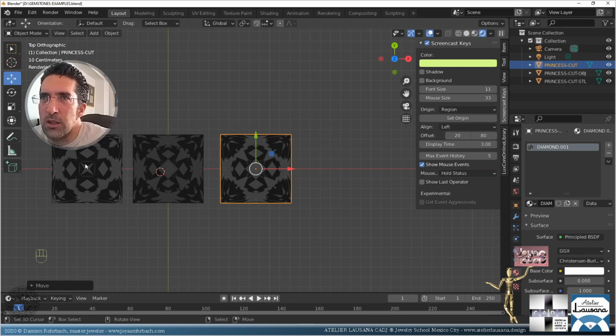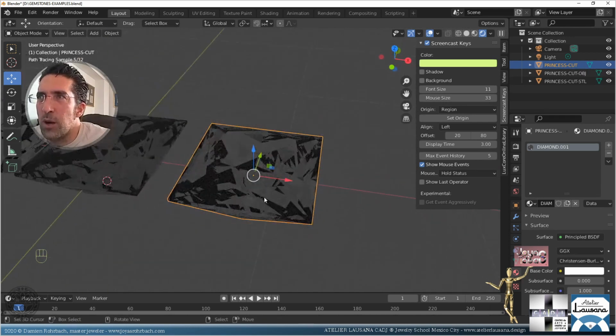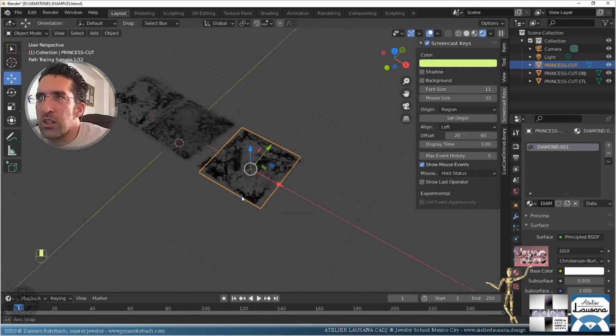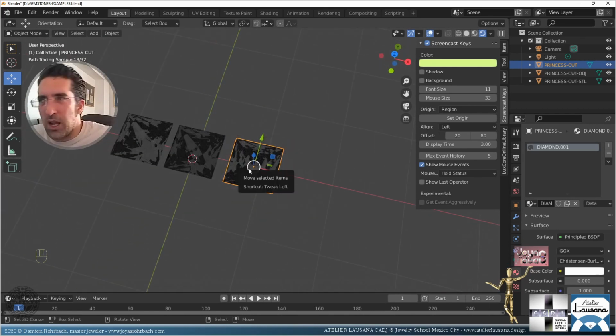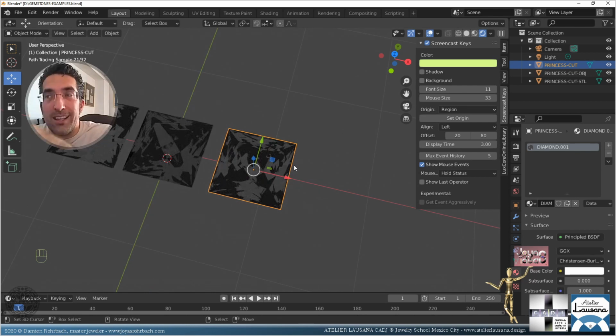If we can see the left one, this one is the object, and we can see slight differences. So even the object export changes somehow the faces. Maybe it duplicates them. Yeah, sometimes it does. You can merge that anyway. So appending is one of the best ways, and actually when you want the cleanest file, use append.